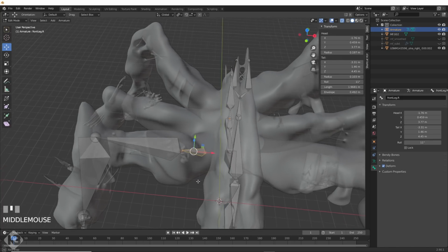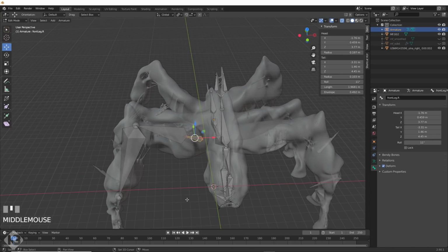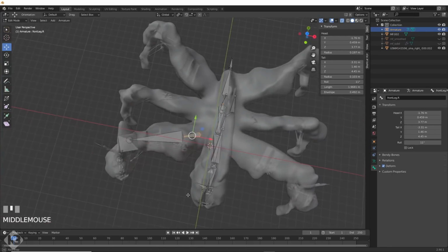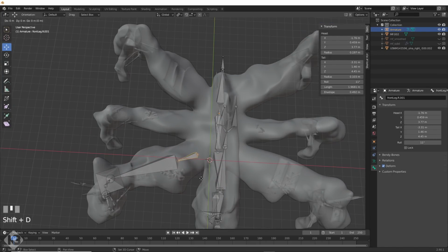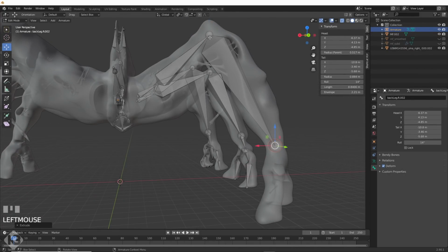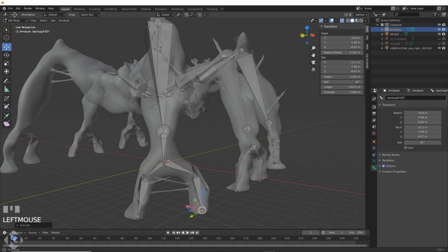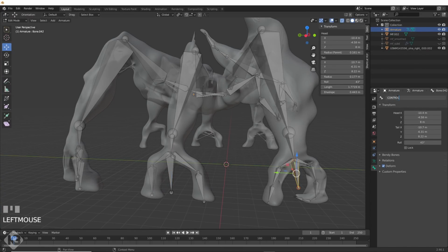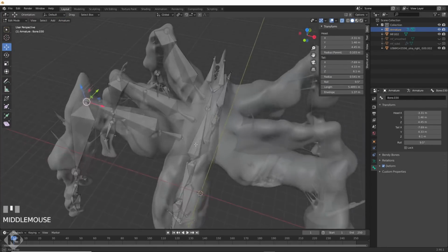If you don't do this, no one can help you. You'll be stuck in suck forever and have a whole lot more manual work to do. I'll show you later. So I made the rest of the right side leg bones, naming them appropriately. Front leg.r, middle leg.r, back leg.r. If you do that from the first bone, the ones you extrude will carry the R down the chain and make things much easier for you.